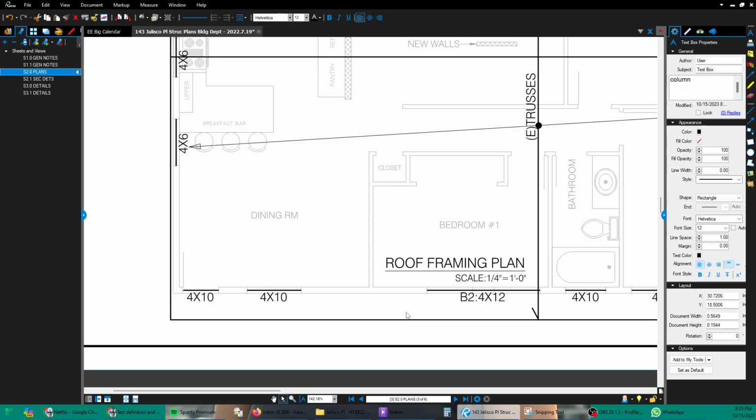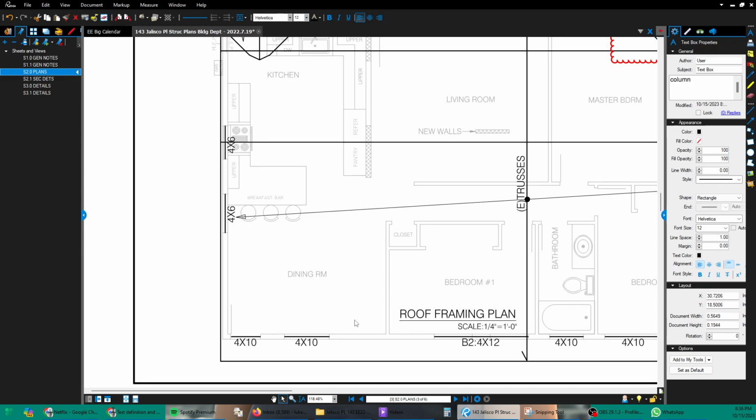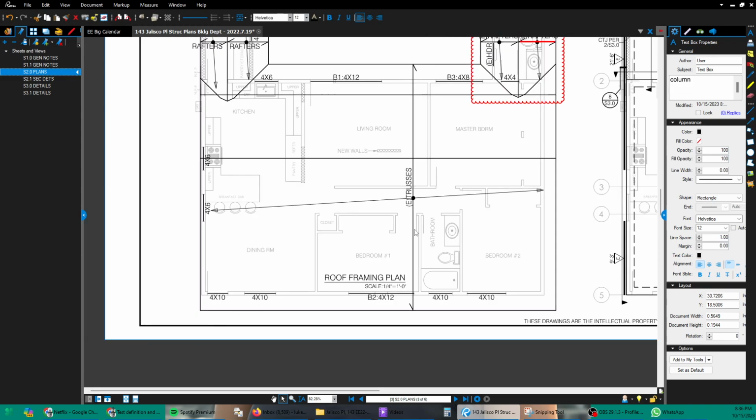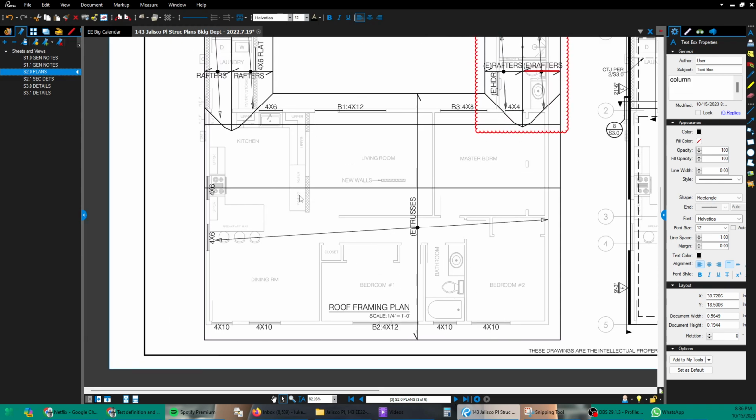We don't want water running down the walls because structures are water resistant, they're not watertight. So if we have the opportunity to get water off or to keep it from touching the building at all, that's preferable to having it run down the face of the wall, stain the wall, and then maybe discover some crack, some leak in the wall, and have water go inside the wall and cause mold. So this is why we have eaves.